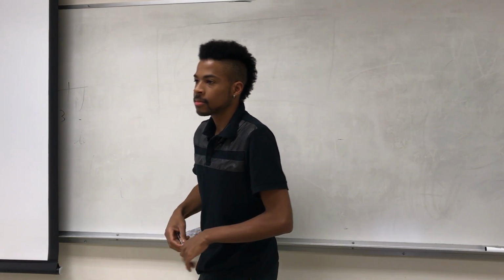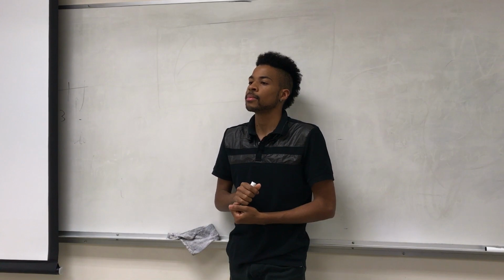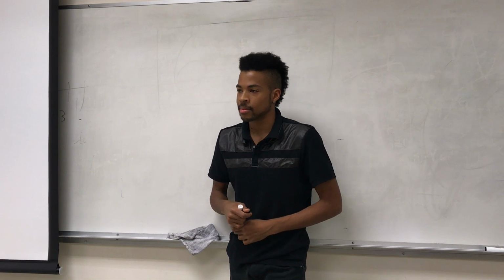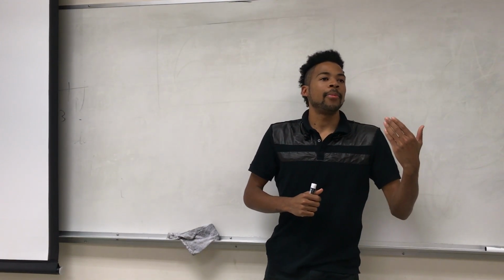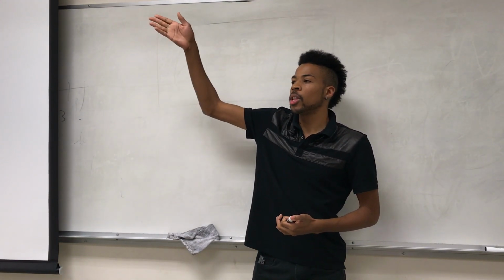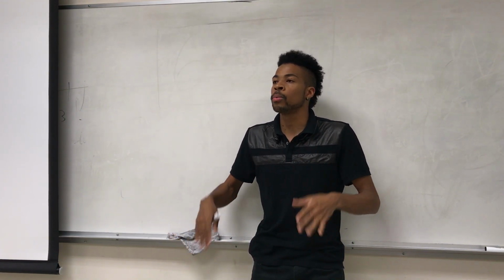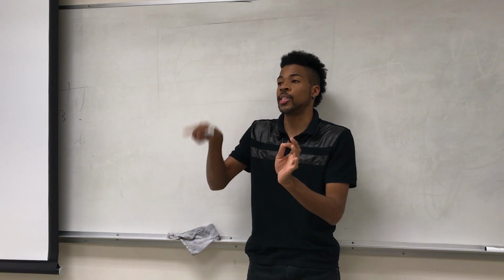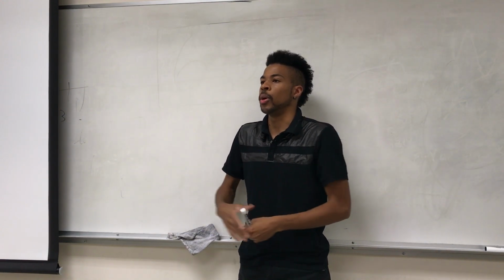So level would be like, at any time if I check the status of this, if it's at this level, then it's considered an interrupt. That is correct. Whereas on the edge, the instant that it happens, that causes the interrupt. Exactly. So for example, the reset pin on your SJ1 board is actually level triggered. When you pull the line low, it's not looking for a falling edge, it's just looking for the fact that the signal is low. Once it's low, because the reset pin is active low, it will trigger and hold inside this reset loop. Once it goes back high, that's when it will begin to reboot.